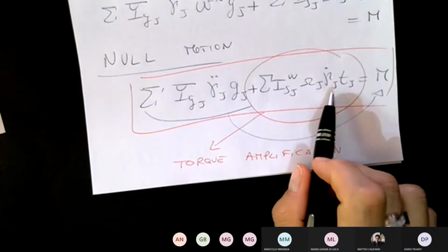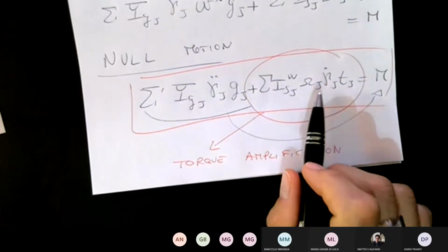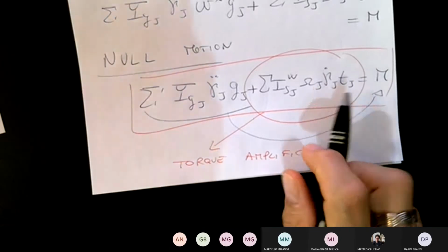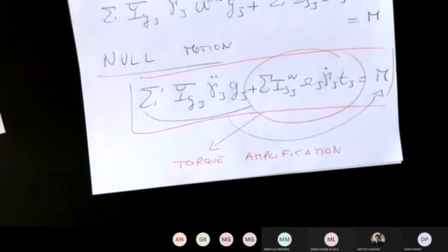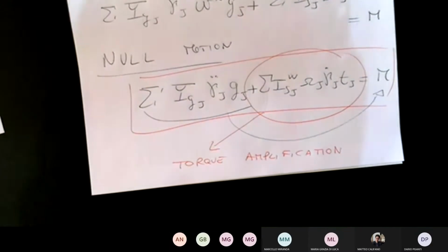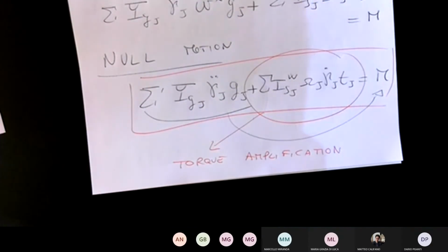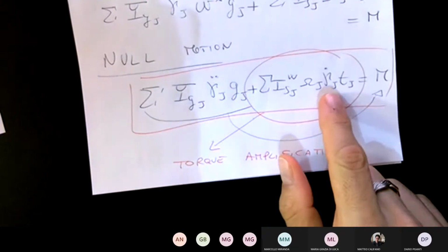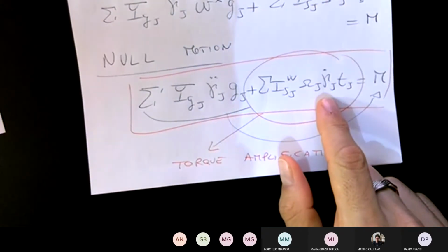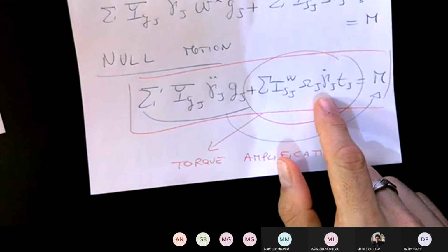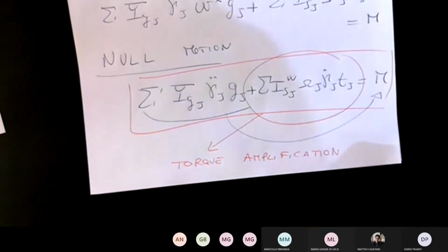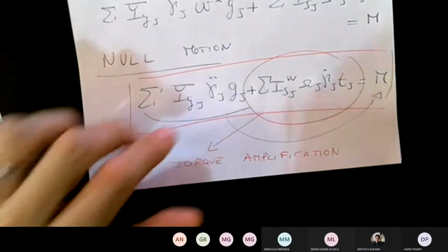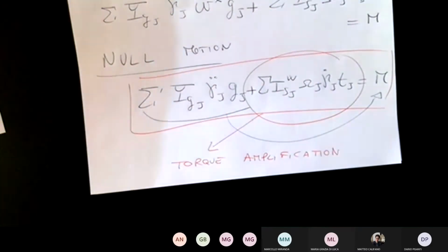So the advantages of a control moment gyro are several. They usually give you more torque for the same size of the spinning wheel, which means that for the same torque you can actually have smaller wheels. They require less power. You're really just maintaining the RPM of the wheel and slowly changing the gimbal position. And so there's less volume, less mass, less power for the same torque.